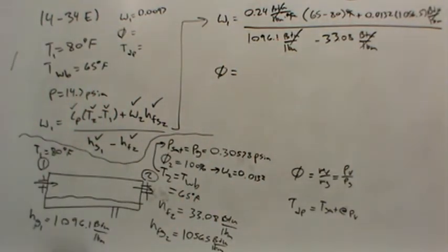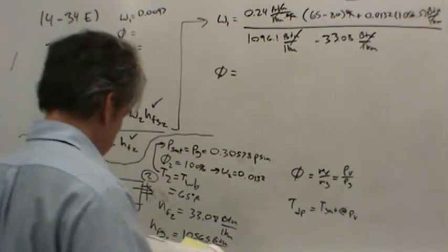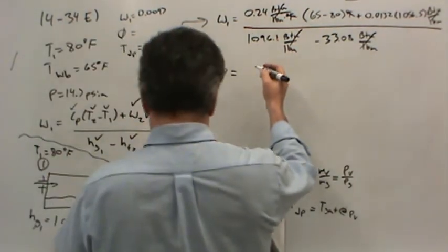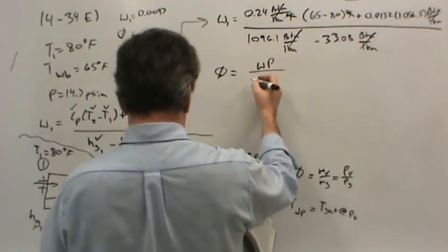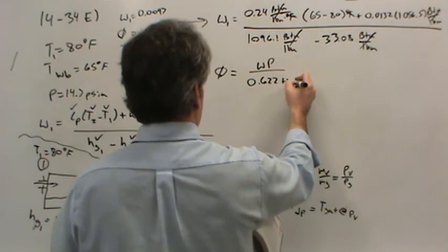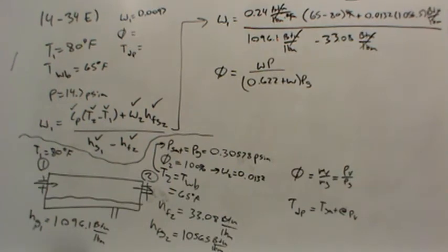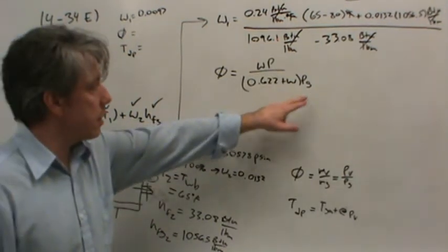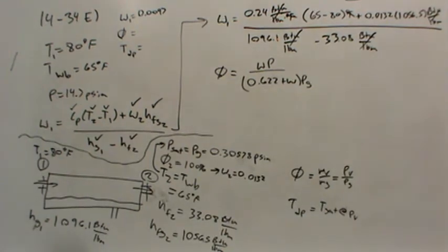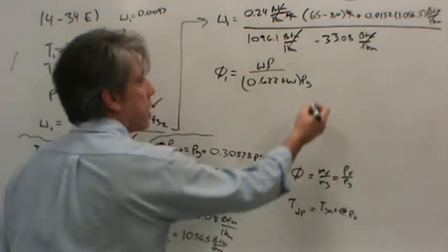Well, now that we've got the absolute humidity, getting the relative humidity is actually straightforward. Go to page 754. You see this equation? It relates the relative and absolute humidities to one another. Okay. Well, that's nice. Are we going to use this PG in it? No. We are interested in state 1, so we better use PG1.